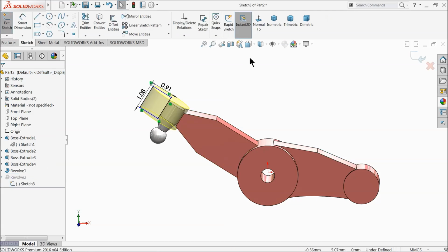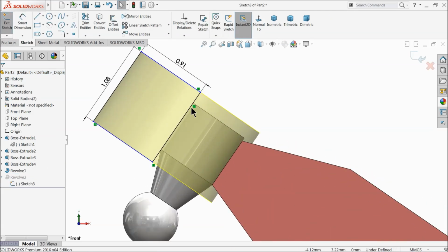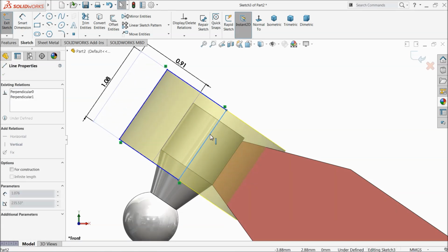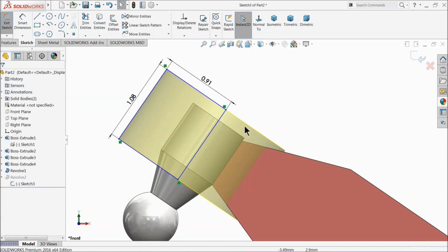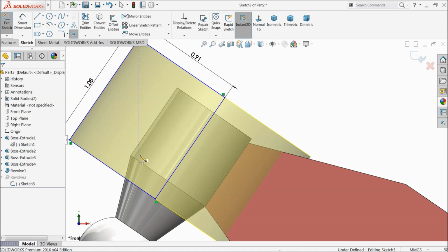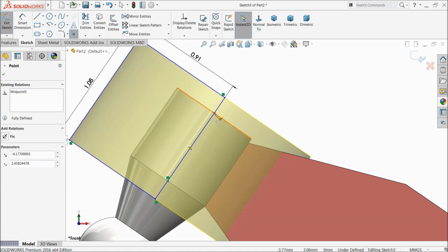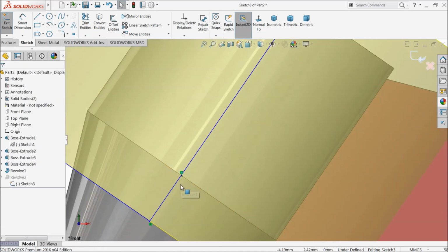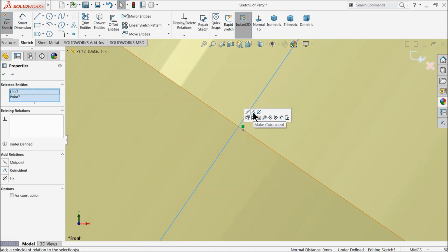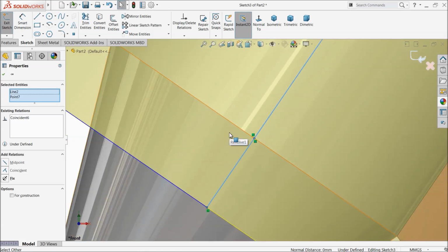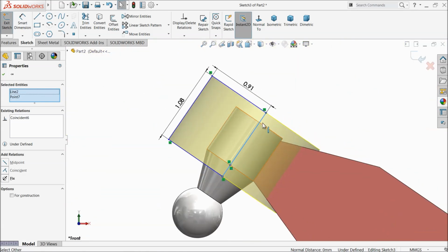Edit sketch, normal. Now delete this relation and drag this one up to midpoint. Choose here center point and define this center point. Exit. Now here select this center point and this one, go inside. That's it. Now this is the midline of this one. Okay,